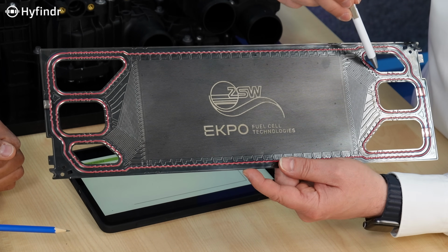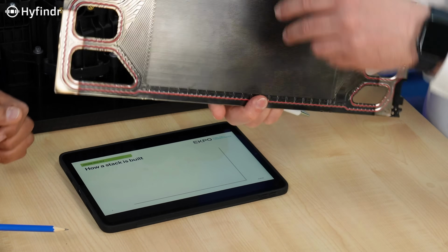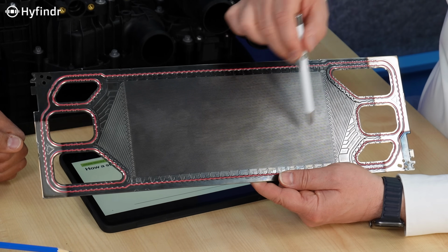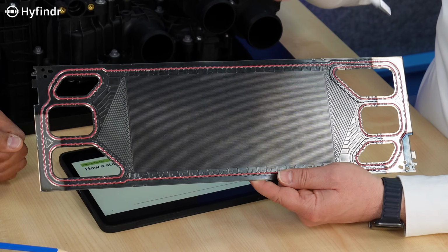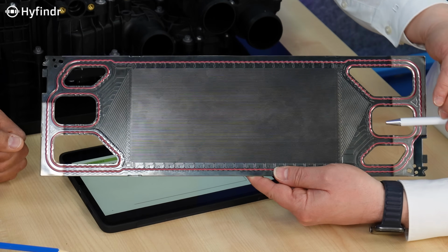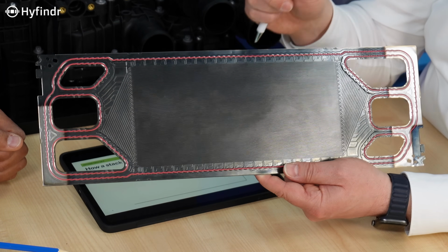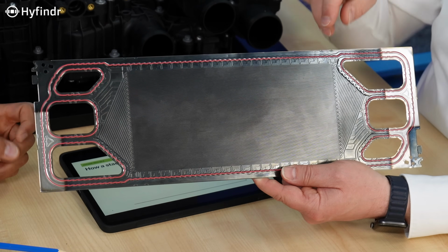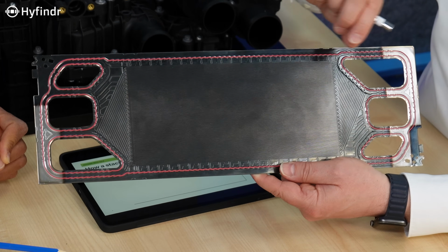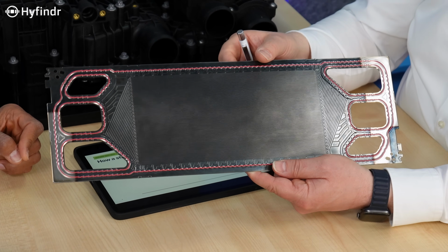Okay. So hydrogen is entering here, is distributed, exiting here. Okay. So on the opposite side, we have similar for the oxygen. So the air is entering, is distributed, and is exiting here. As we also produce heat in the reaction, we need coolant. So coolant is entering here between the two layers. What we actually see is two layers of stainless steel, which are stamped and then laser welded together. And they have in between some volume where the coolant can flow and can cool down the chemical reaction.